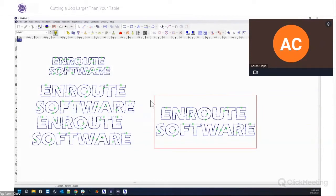So that's what the clip to plate does. It says any toolpath, irregardless of what it's connected to or where it's at, if it goes outside of this boundary, it gets cut off. So if you have this style of workflow where you like to save variations of the same artwork inside the same file, you can turn that option on, and you can still have them already toolpathed, sitting on the side, ready to swap in and out if you want to. Or if you prefer the other workflow, that works as well.